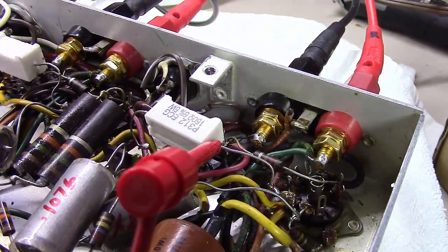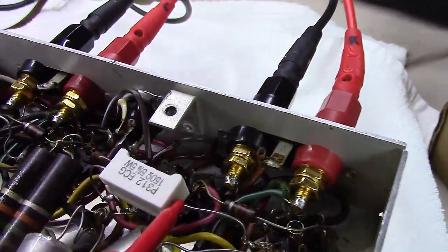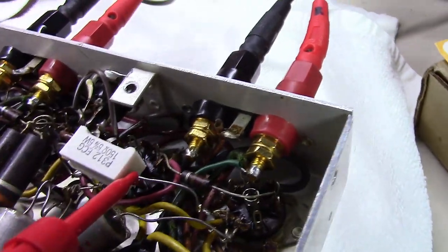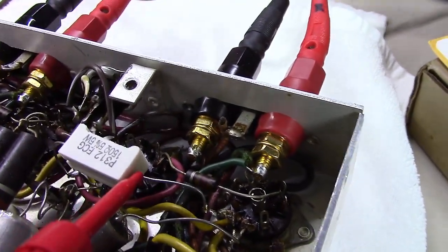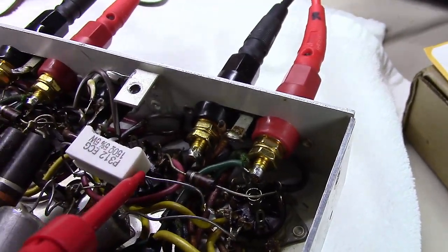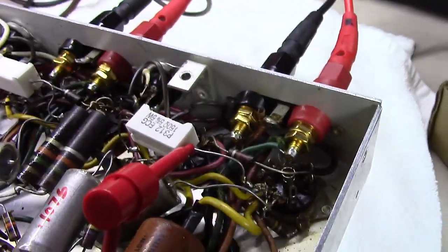If you do 10.76 divided by, this is a 150 ohm resistor, if you can read that on here, you do the math on that, it comes up to about 71 milliamps of current actually flowing through that resistor right now. It's flowing through one side, going to the other, going to ground at this point in time. Let's find a few other points to measure and give you an example.